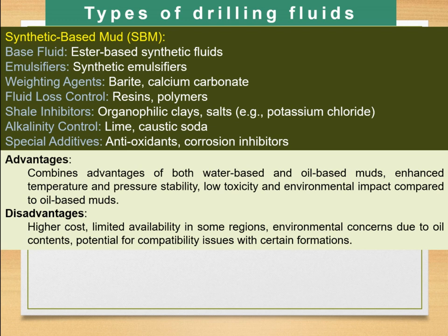Antioxidants and corrosion inhibitors. These are special additives, a special feature with this. Often the drill pipe may be corroded in certain circumstances, so those things can be avoided here. It combines advantages of both water-based and oil-based mud in case of the synthetic one. So it has enhanced temperature and pressure stability, low toxicity and lower environmental impact compared to oil-based muds.